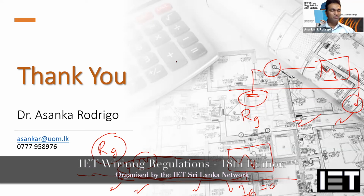I went to one of the bigger multi-story buildings, where the client asked me to come and check. They have a dedicated transformer, and it's in Colombo city, where one of my students is an electrical engineer. The people on site said that the CEB people came and put two different earths. I said it cannot be, because as I know they are not putting two different earths. It should be a single earth, even for the body, and the neutral earth should be the common earth. But they said, no, see, they have put two different earths.